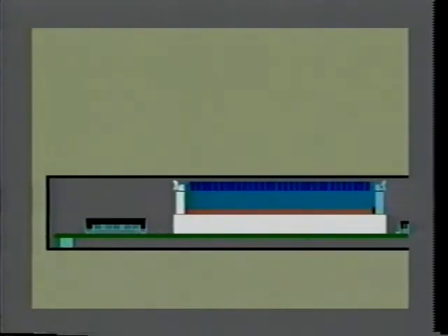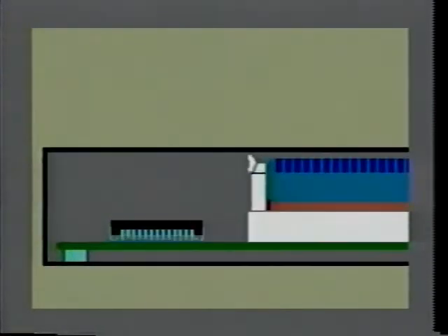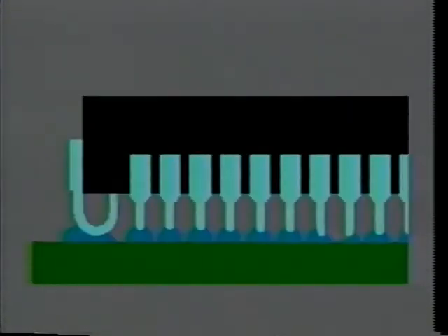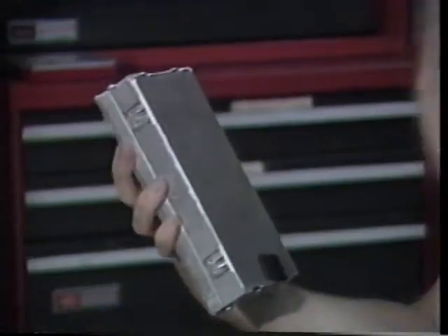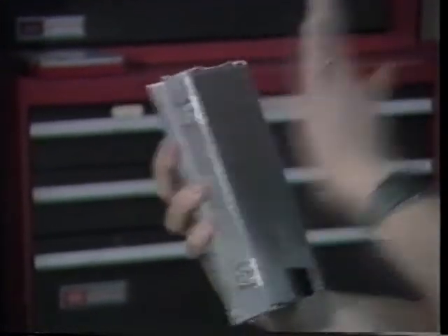Here's why. Some of today's integrated circuits are surface mounted, that is soldered to the top of the circuit board, not through the board. Also, there can be up to 52 pins soldered in a very small area. Any flexing of the circuit board places the IC solder connections at risk of damage due to mechanical overstress. Such damage might show up immediately, or it might show up later. Circuit board deflection can even occur as a result of striking the ECM just using the palm of your hand.